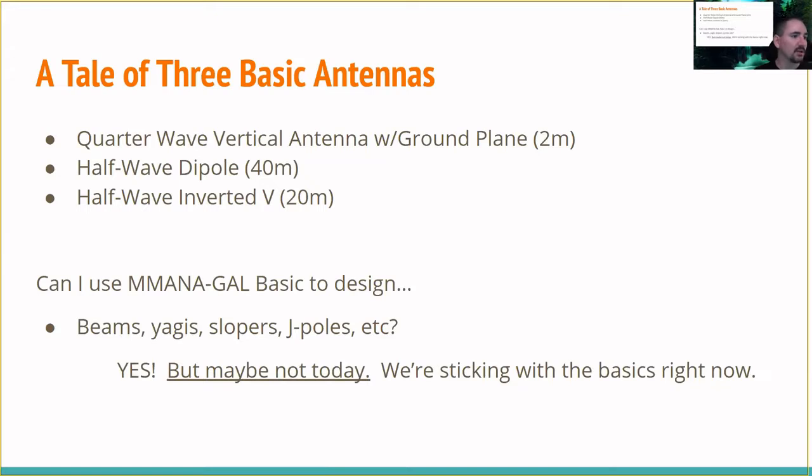We're also going to talk a little bit about a half wave inverted V 20-meter antenna. And this is one of my very favorite antennas, because a half wave inverted V at 20 meters can be built out of $3 worth of materials, hoisted on a painter's pole, and you can put it up camping. You don't need any fancy towers or balun or anything. It just works. I actually have talked to Slovenia on one of them from my front yard.